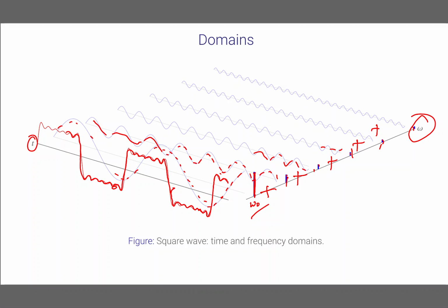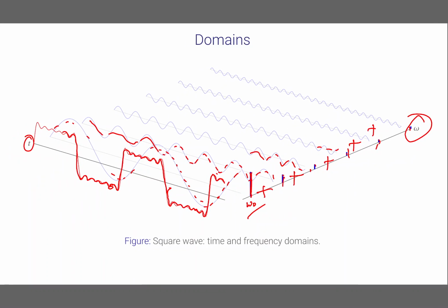Okay, so what we did today was understanding what signals are. They are actually functions of independent variables. We considered functions of just time, or a single independent variable. Under signals we have continuous time signals, which we denote by x(t), and discrete time signals where n is an integer and we use brackets to represent that.